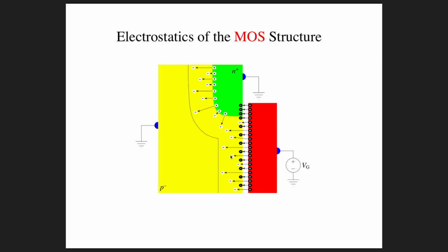The ionized acceptors have the same density as the hole density because basically these holes came from the ionized acceptors to begin with. And so when the number of electrons in the channel is few in number compared to the ionized acceptors in the depletion region, we say that that's weakly inverted. So we've got some opposite type of mobile charges here at the surface, but their density relative to the ionized acceptors is small. And so that's called weak inversion, and that correlates with subthreshold operation.